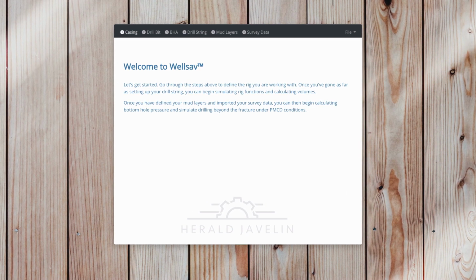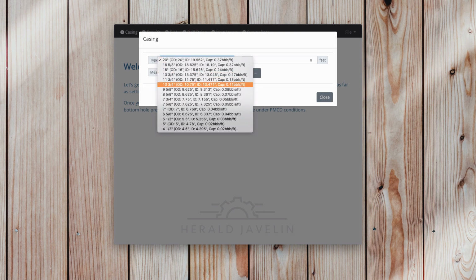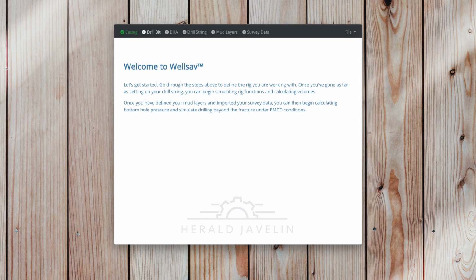Let's first off say, and I should say most of my drilling experience is taking place in Kazakhstan, so this simulation is going to simulate rough drilling conditions as they were in Kazakhstan. So let's say we have decided we are going to set our 9 5/8 casing string at, let's just say 10,500 feet. Okay? So we're from surface to 10,500 feet with 9 5/8 casing.